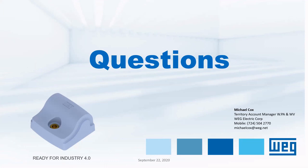Yeah, absolutely. Our sensor can be used on any brand of motor, any manufactured motor, as long as it's cast iron and it has a ribbing on the frame. So what you can do is drill a small hole into one of the ribs.